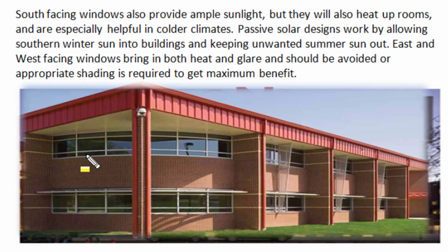North facing fenestration provides ample amount of daylight, but it won't contribute anything to heat up internal space. South facing windows provide ample amount of sunlight, and they also heat up internal space, especially during the cold winter season, and shading by horizontal projection on fenestration restricts summer heat from penetrating inside this south face. In passive solar design, this horizontal shading keeps unwanted summer sun out, and the same sun radiation in winter, which is at a lower angle, is allowed into the building by this fenestration.